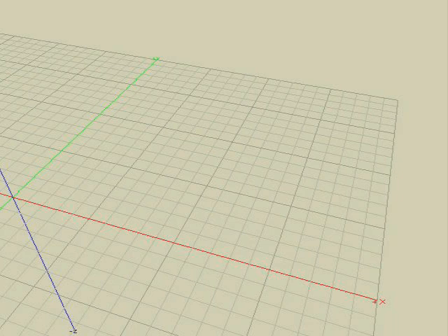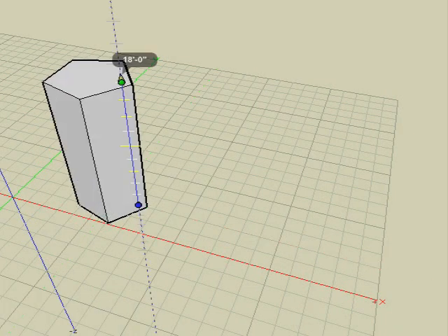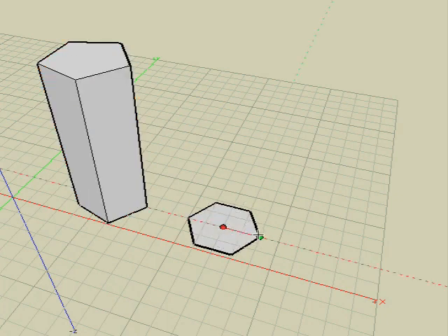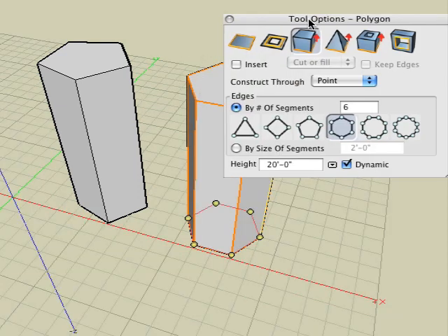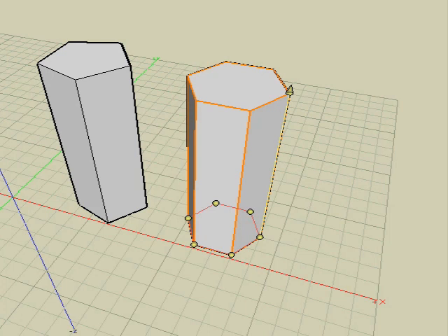The third and final operation we'll discuss in this tutorial is the Triangulate tool. It's used to triangulate non-planar or all faces of an object. In this example, we extrude a pentagon and a hexagon with the Polygon tool from the Draw Suite of tools. When drawing a polygon, note that its number of sides is determined with the pattern icon shown in the tool options palette. We'll use these objects to perform the triangulate operation.